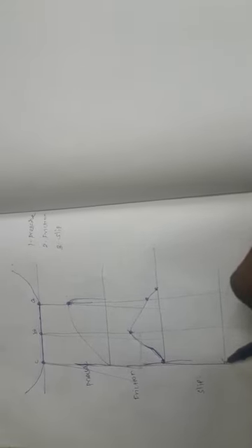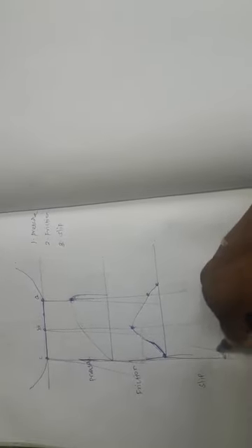So you can feel maximum slip at the trailing portion of your foot. What about points A and B, the leading or loading portion and the center point? You cannot feel any slip at A and B, you feel slip only at point C, the trailing point of your foot or of your tire, right? So the slip will be maximum at the trailing portion.